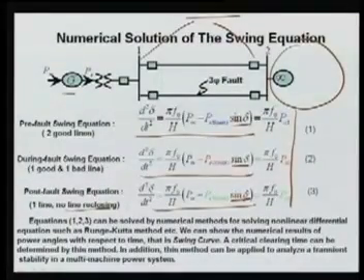Sometimes all the buses that are not connected to generators we try to eliminate. We'll see that in later sections. Here they will be eliminated, and only the generator terminal buses are kept intact, along with where the fault is occurring, and then we can analyze the system behavior. That means we can see the relative motion of the individual generators with reference to any particular generator, and then we can say whether the system is stable or not stable.